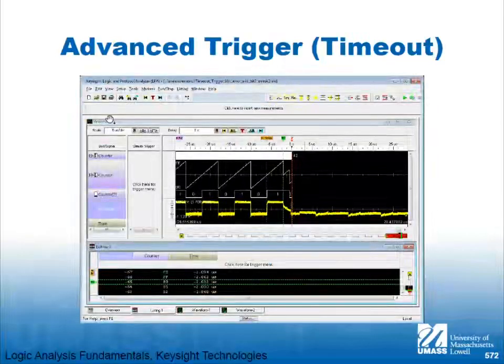So here's, for example, the trigger event, and we've set the trigger to see that's a T right there. We set the trigger to this point, and we set up a trigger that would sense the fact that the counter had stopped counting. Set a timeout, and that's how we get triggered here. Great, that's what this was looking for. We're not going to use that method of triggering.